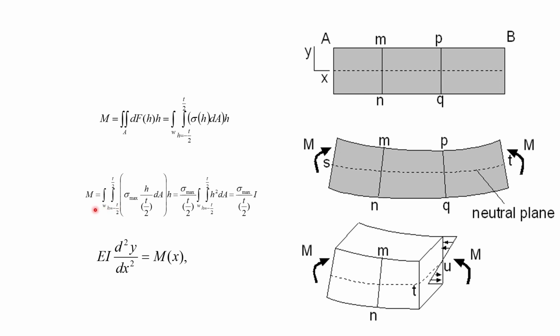Using the torque balance equation, the total torque has to be equal to the maximum stress, and you can estimate the stress as a linear distribution where the stress is zero in the center, in the neutral axis. So you can integrate the stress multiplied by the area to counterbalance the M. From here, one can calculate the maximum stress. The maximum stress happens on either the inner or outer surface, but no matter what, it is happening at the surface of the beam.